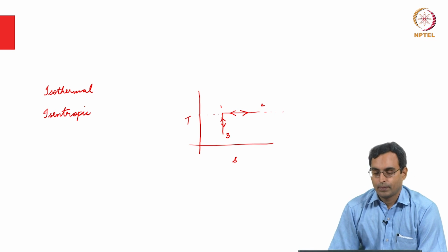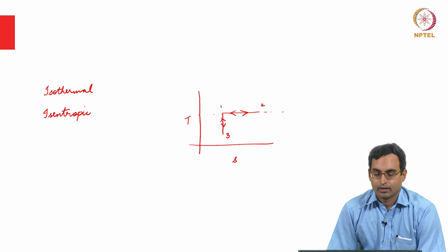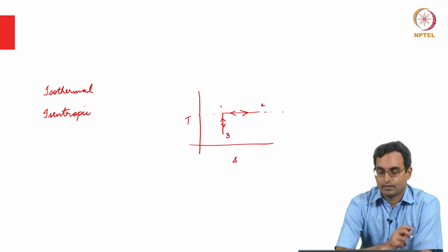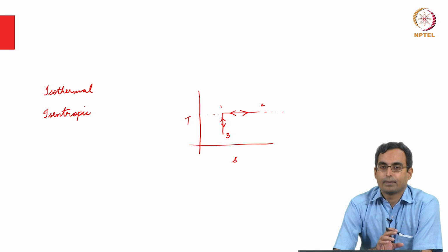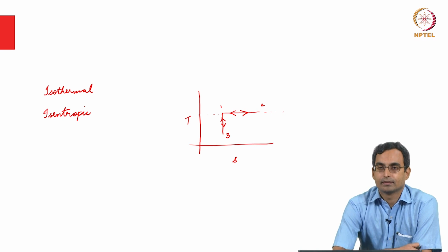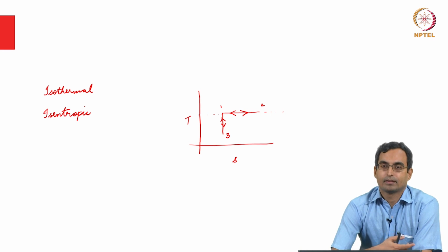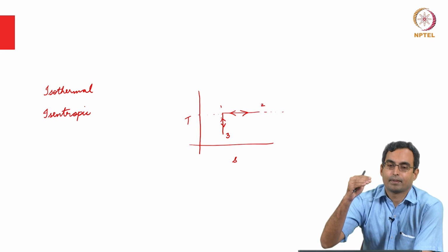What we discussed also is that we can have irreversibilities if we have temperature gradients or temperature differences over which we transfer heat. So, we said if we have a finite temperature gradient, then heat transfer across that is irreversible, because if we want to transfer back the heat, we would need to run a heat pump, because the second law says that we cannot transfer heat from a low temperature to a high temperature in a cycle without doing work.